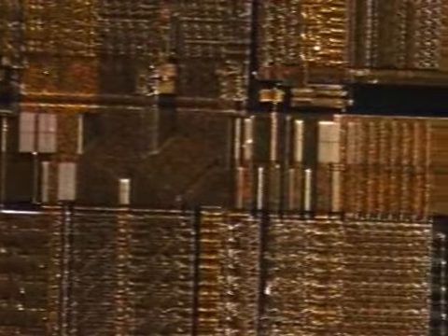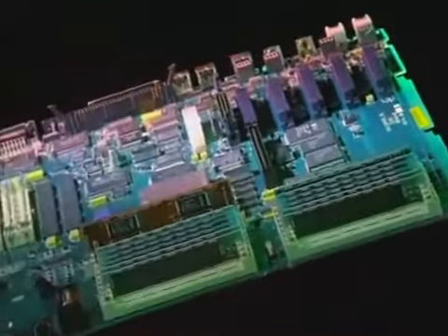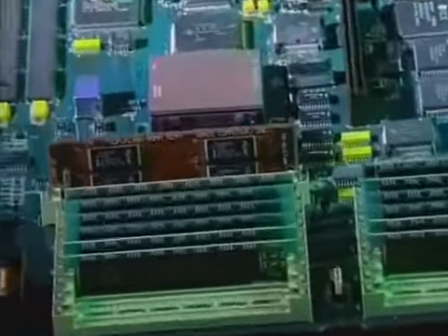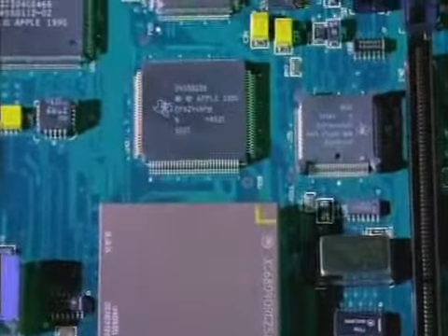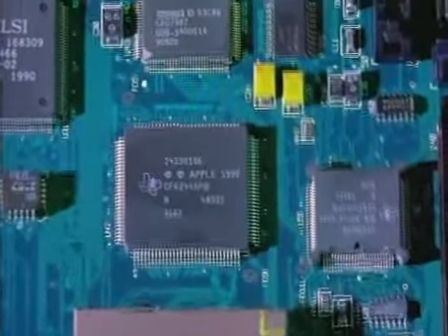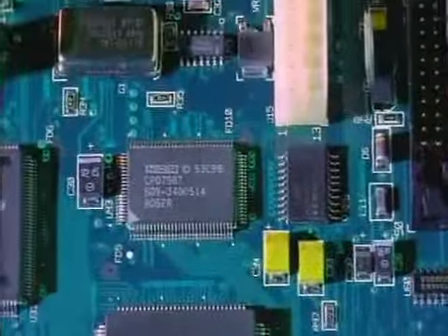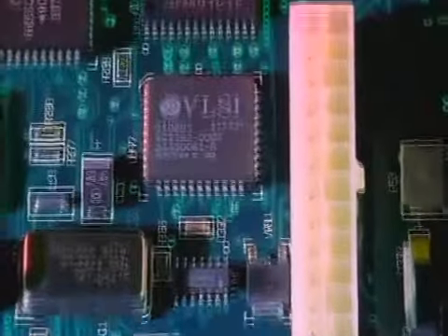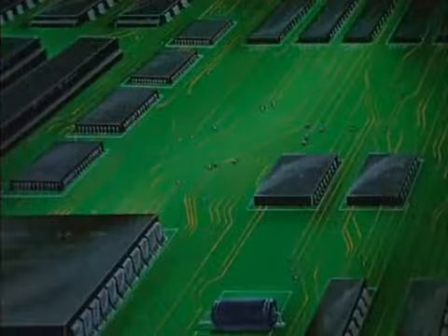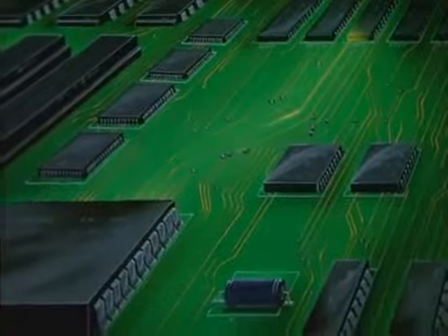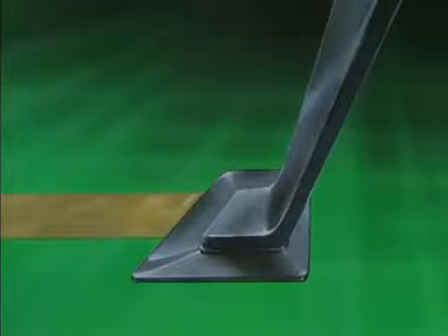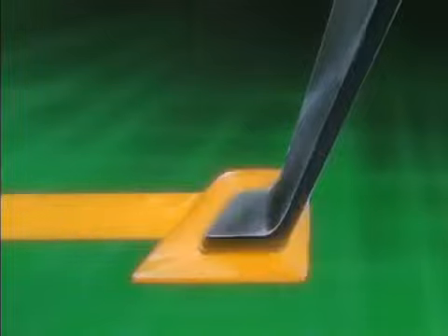Most of the speed is lost, though, on the circuit board, where the signal faces an obstacle course of long transmission lines, inhibiting materials, and the chip's packaging. As the signal travels from one chip to another, it encounters increased capacitance in the large surface areas of the pads, the solder, and the metal leg of the packaging. The most difficult are the thin wire bonds, which resist the flow of current.